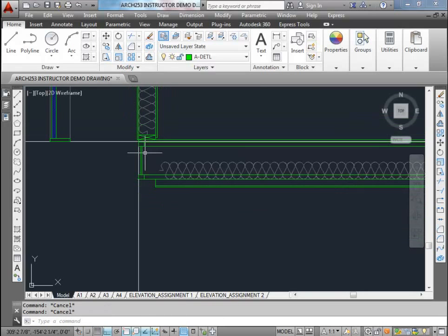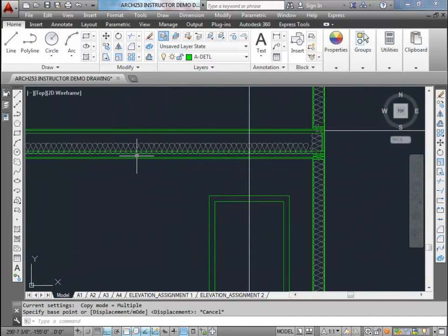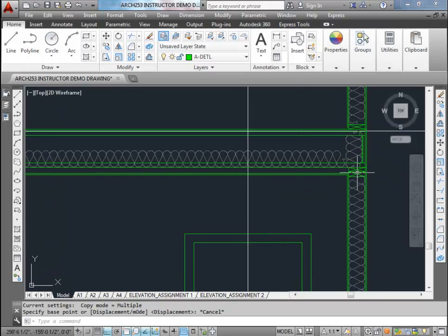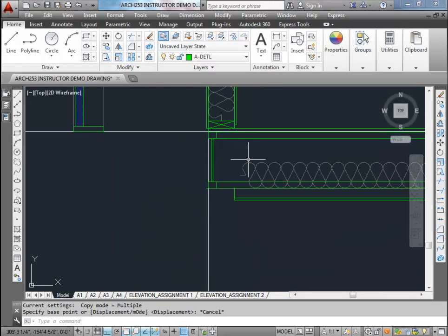Now, in the longitudinal section, we're actually going to see these joists, and we're going to see them all the way across. Longitudinal section shows the joist all the way across. We don't show that in the transverse section because we're actually looking at the side of one of the joists that would go from end to end. So it's being supported by the wall on one side and the wall on the other side, and you're just seeing the length of that joist. But in the longitudinal section, we're going to see each of those joists coming towards us.